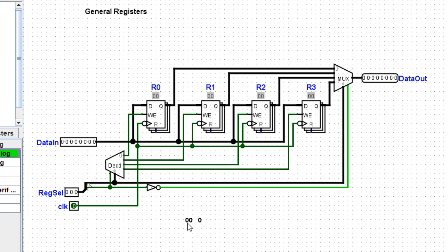And it's the 2 low order bits. I've got this backwards, so let me just change that. I don't want to confuse anyone. The 2 low order bits are used to determine which of the registers are going to be active. Since I want to move load immediate into register 0, these 2 bits need to be set for 0, just like I've illustrated here.